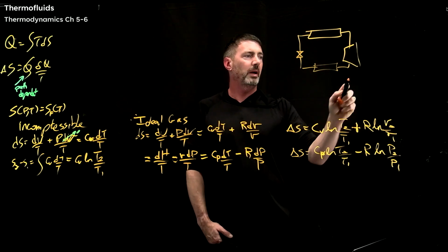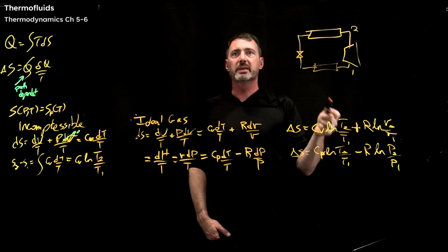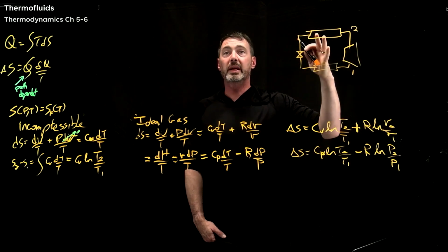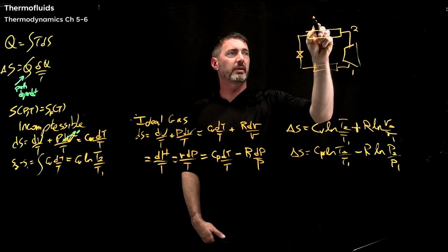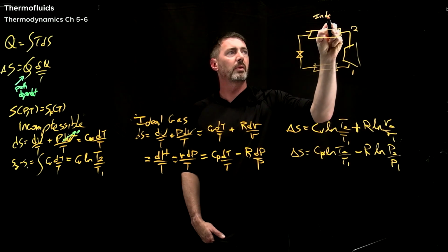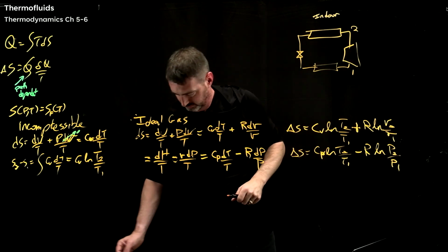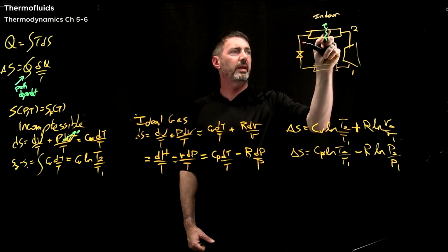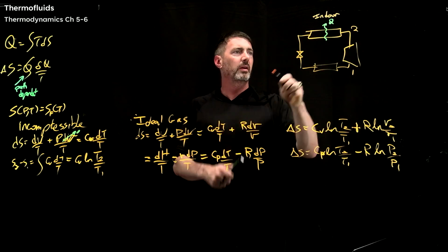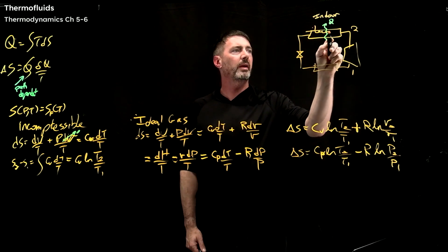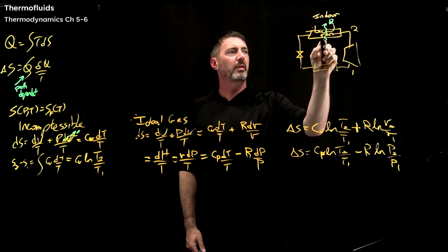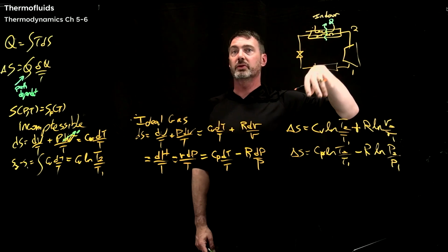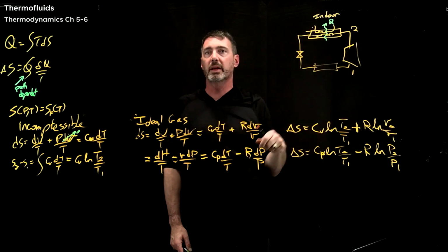What a heat pump is going to do from 1 to 2 is raise the pressure. And then this is your heat exchanger, so this is in your house, or indoor. And this is now hot. And so what's going to happen is you're going to flow air to exchange heat with this hot refrigerant that's in it, and heat is going to flow from this really hot refrigerant into the air, and then heat your house.